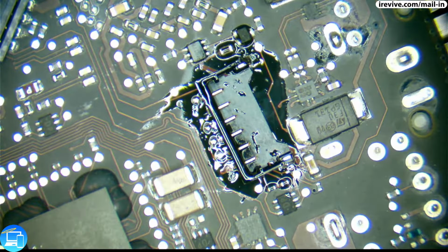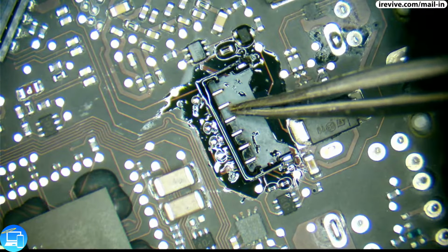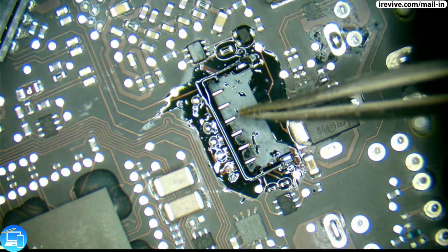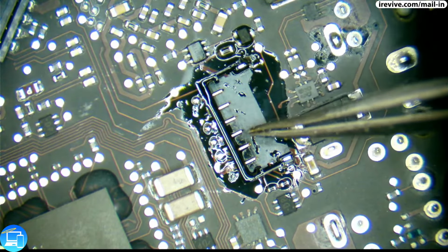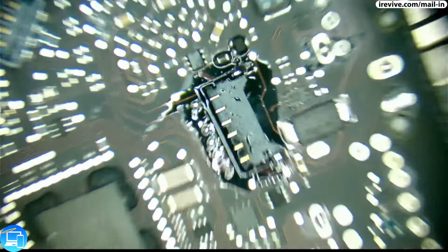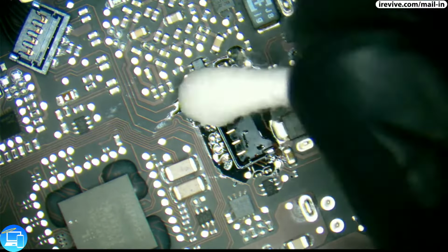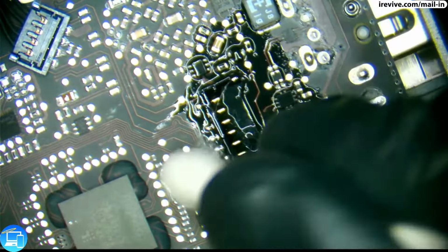And then if you'd like, just to make sure that they're actually on there solid, do a wiggle test. Just kind of poke, and if it feels like it's wiggling more than it should, then you might need to solder again. And these all seem pretty fine. So we're good there. Let's go ahead and just clean that up a little bit with some isopropyl alcohol. Just put a little bit of isopropyl alcohol on a Q-tip here.